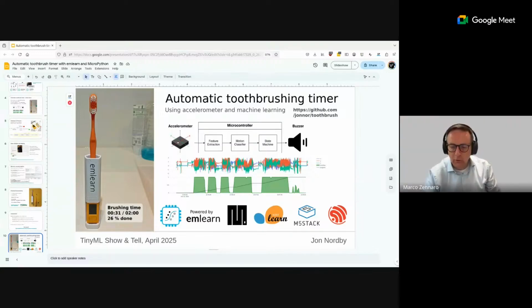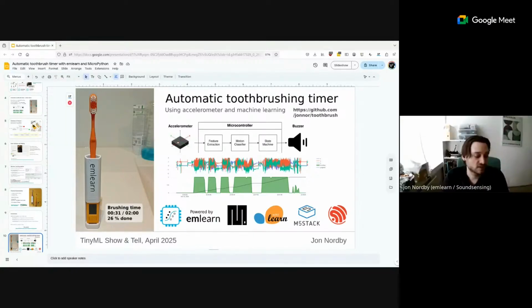John, you mentioned low power. So how low would it be? Oh, we'll see exactly, but in the low power state, you would basically turn off the microcontroller and let the accelerometer run. Those do just like 5 microamps, and because you can do a low sample rate, I think 10 microamps, 20 microamps, something like that in the low power state. And then it depends on how much things are moving around, and how often you go into a slightly higher state to check what is maybe going on.